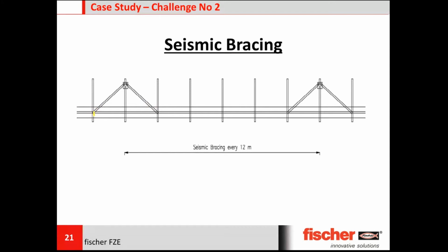We thought about interconnecting three normal supports like this. What you see now is the plan drawing. So we connected support number 1, support number 2, and support number 3, so that in the event of an earthquake, they are all holding to each other, positive of this support to the negative of this support to the positive of this support. So it balances each other. So when you have an earthquake, the pipe will stay strong.